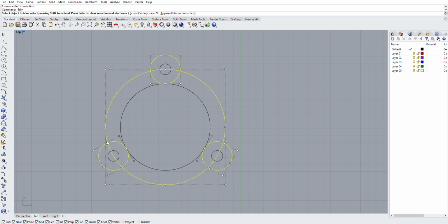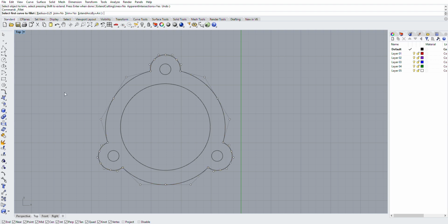I use that command more than just about anything. We can go in, remove all of these, and go back to the fillet tool. I wonder how that's pronounced all over the world. But use the fillet tool, and since this flange is just being made out of nothing, the radius on the fillet doesn't really matter. This is more aesthetics and a little bit of strength.